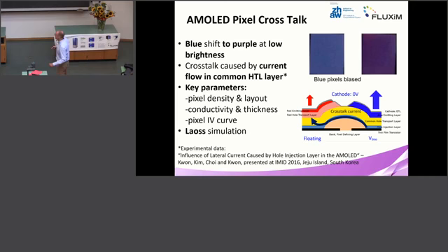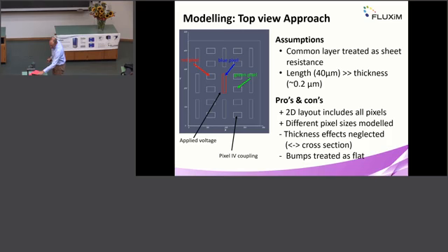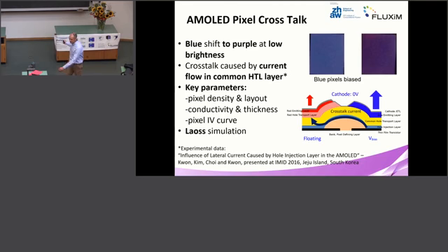And so in our 2D plus 1D modeling concept, we have this top electrode as the one 2-dimensional electrode domain, and the bottom electrode is a unification of metal plus conductive p-doped layer. We also made the assumption that the bumps, this yellow bump here, which is a pixel separation wall, are simplified and everything is assumed flat.